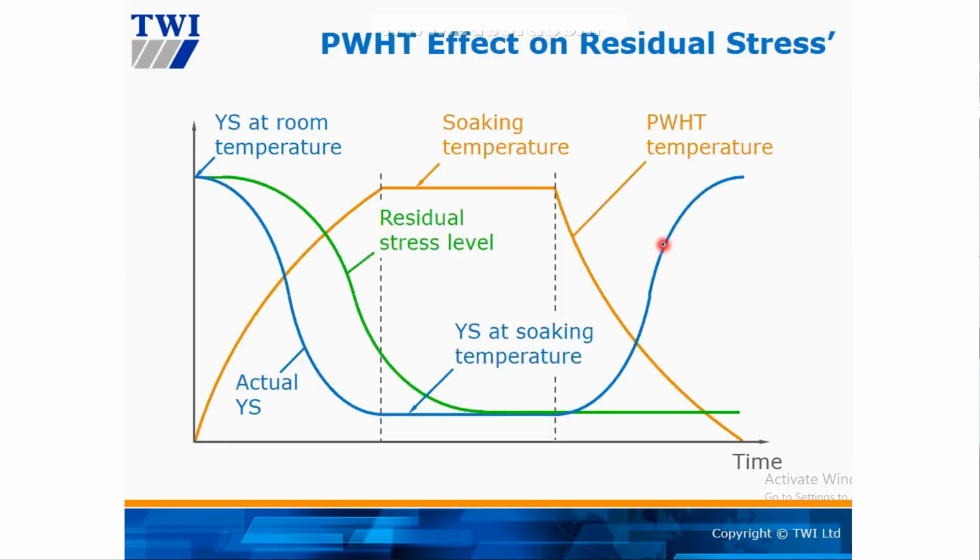And this one we talked about yesterday in stress and distortion. So again, we have heating, we have soaking, and then we have cooling. Here residual stress goes down at soaking time, lowest level. After cooling, it's at a lower level. But for elastic strain, it goes down during heating, lowest level during soaking, but it will increase during cooling.